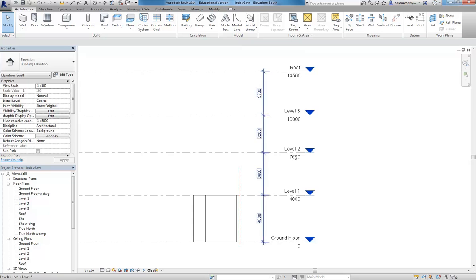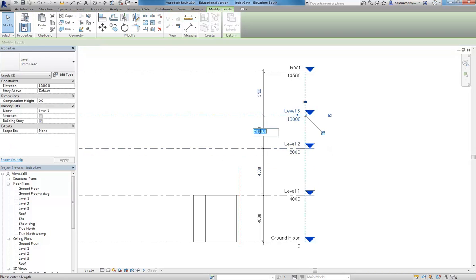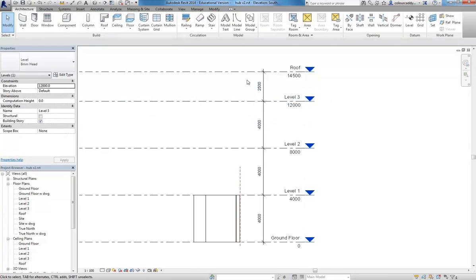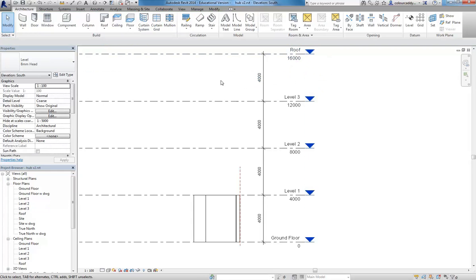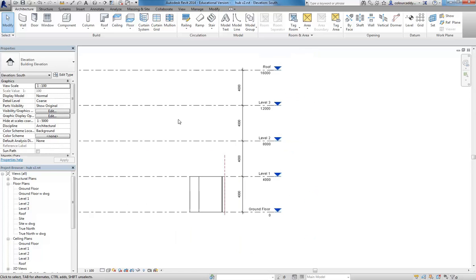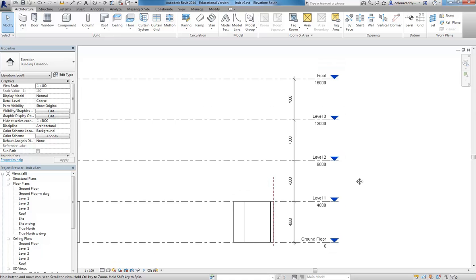So here, what I'm doing is just matching the heights of the levels. That's just a little thing, which if you can do at first, in other words, if you can have the levels all with even heights, where possible, don't worry if you can't do this, but if you can have them like that, it will just make it easier for you when you're copying things between levels at first. It really can help a lot. So try and do it like that, but again, if your level heights are already on your section and you put those in and they're different, then don't worry too much.